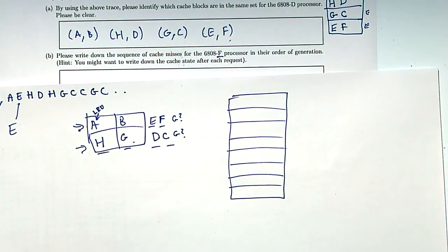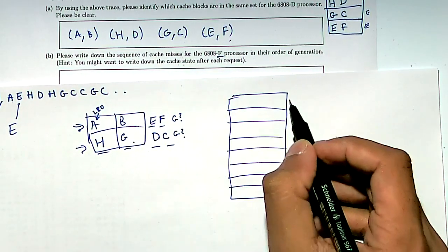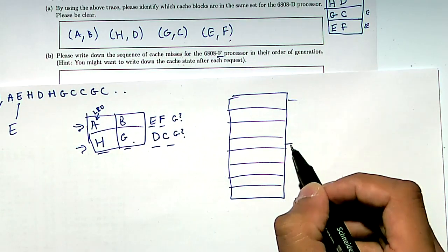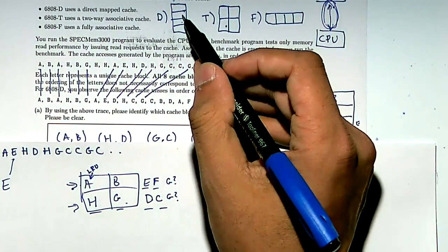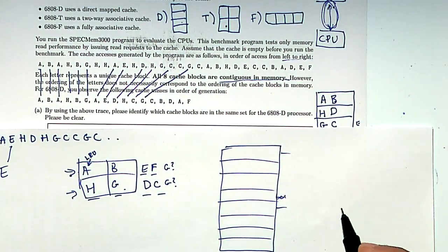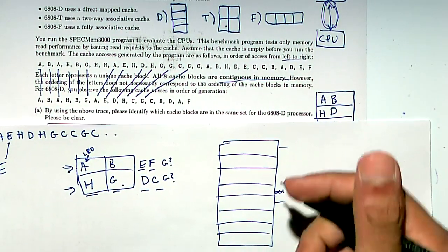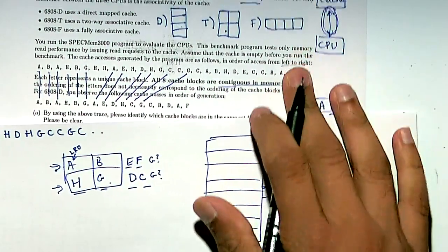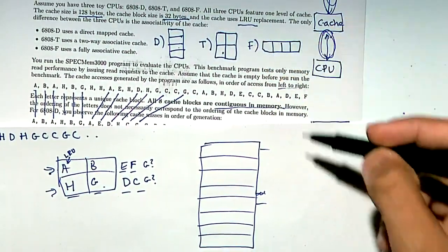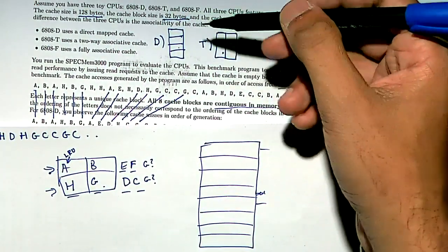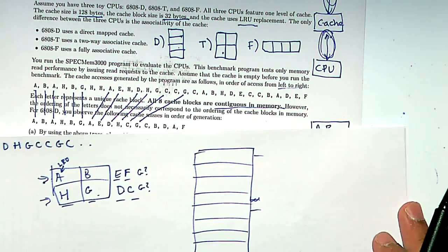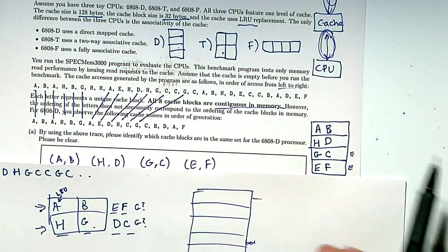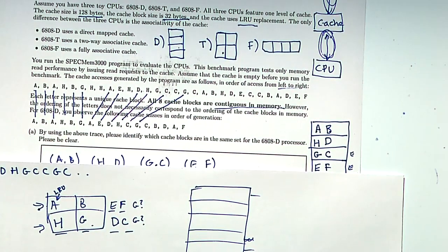It's all about A and B having to be off by 4 in order to map to the same set over here, because you're using specific bits of the address. So it's like modulo 4. And here, this is modulo 2, so anything that's modulo 4 is going to fit into here, and they're going to map to the same set here as well. So it's pretty important that the 8 are contiguous, because if they weren't, then you'd have no way of really knowing anything.